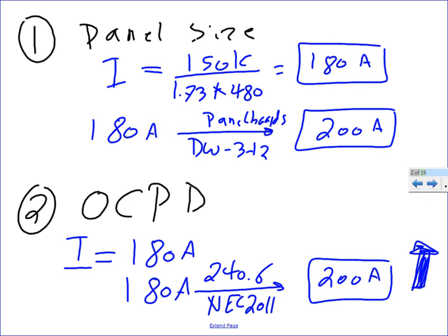Up to 400 amps, going up is not a big deal. When you go higher than 400 amps, 600 amps, technically you have to go up. In the test, I want you to go up. Safer, you go up. Am I clear about this point? Engineering judgment, you have to use your judgment. If you go down, your reliability suffers from nuisance tripping, and it's not safe.